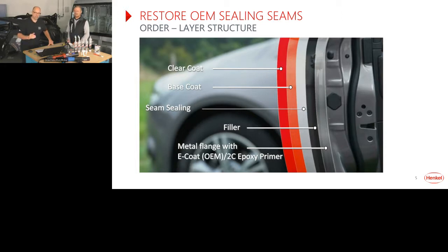To make it conservative, I would say it's good to have it there, because the more layers you put on top of your sealer, the longer it takes to cure it. Okay, because you close the layers. This is one thing. On the other side, you have a very good corrosion protection if you build it up front first. We trust the corrosion protection ability of the painting system, and we put our sealer there in between. Maybe there is at the end of the presentation a slight hint how we can make it in a different way, but let's have the surprise open. So we will see.